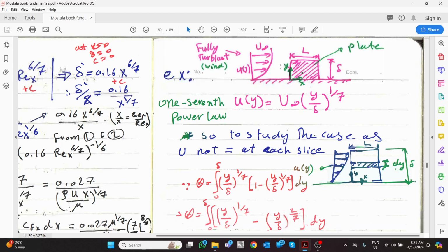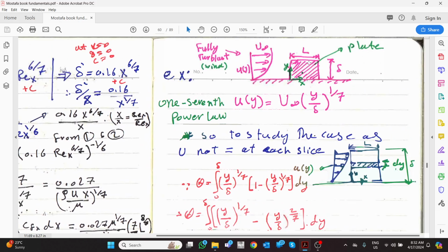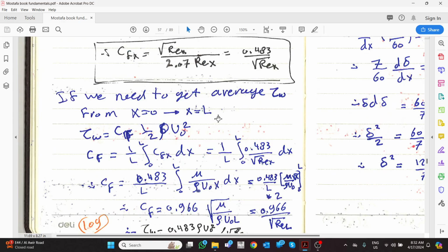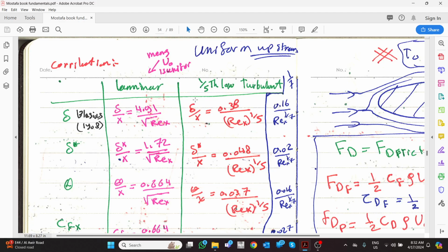And it is going to have a reaction with the plate. Now we need to ask ourselves, same procedure, we need to take the coefficient, the forces acting here, etc. Before starting, you cannot make two solutions, you cannot get the CFx and CF for the wall, for the floor, and then apply here, it cannot be solved. So we are going to go back to the correlations we know, the correlations we discussed to define the wind itself, because we're not going to design the wind itself, but we need to get its equation.